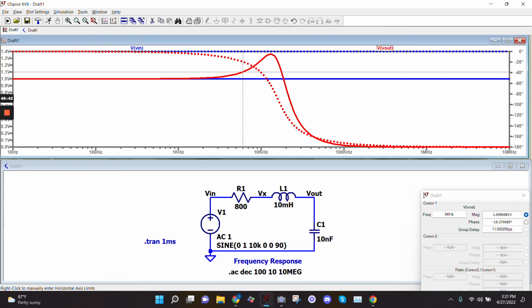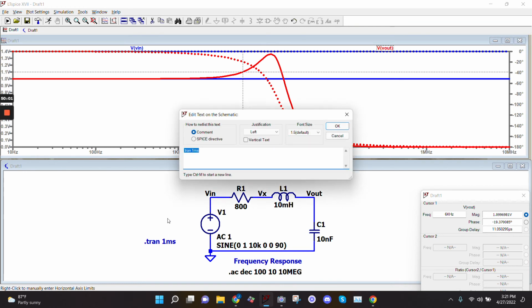Right. The reason I was asking that specifically is because I know for capacitive circuits you have voltage leading, or is it the other way around? For capacitive circuits, the voltage should lag. Right, yeah, it's voltage lagging current, and then the other way around for inductors. Exactly. So let's go back to the transient. It's not going to look very inductive here. Right. It's almost basically purely capacitive.